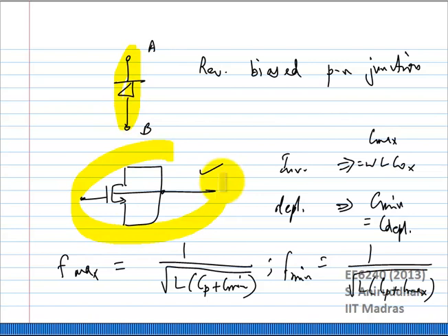The other example is a MOSFET. So you use either the transition from accumulation to depletion or from depletion to inversion. One of these two transitions you use, and it's very common in modern processes to have a dedicated varactor which is optimized for this particular behavior.